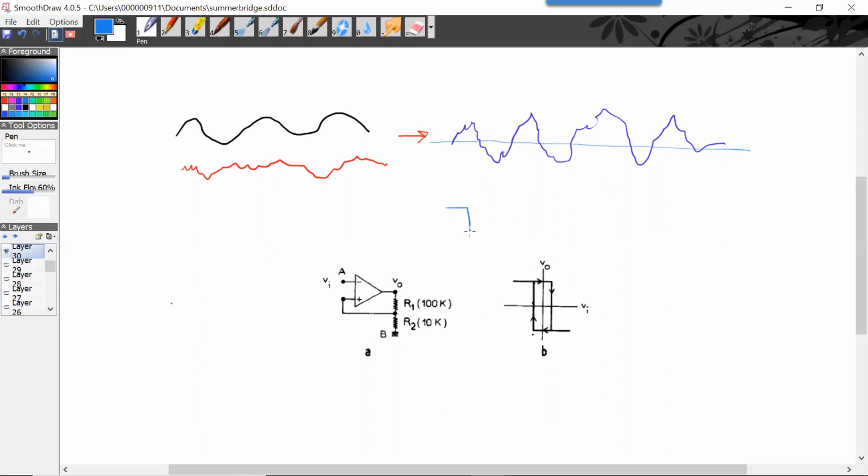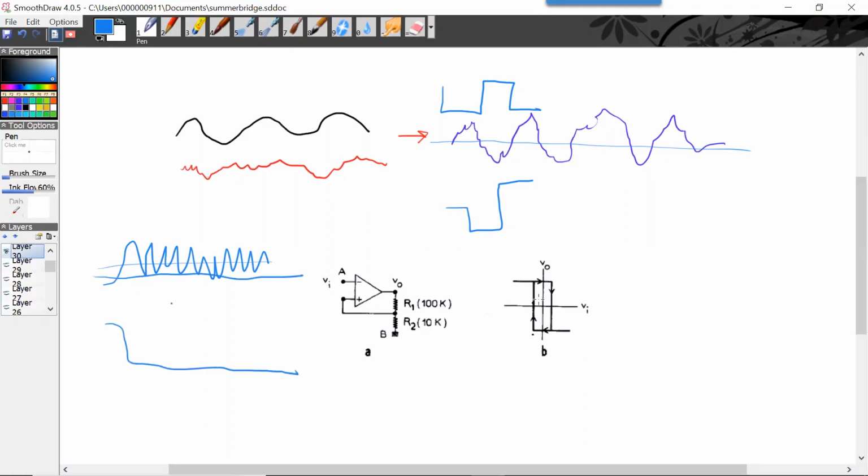is something low, high, low, high, low, high. And the thing is, the Schmitt trigger can actually filter out worse noise than this, where if I'm high and I'm bouncing like that, as long as I don't go below the trigger point, that'll just stay low, right?